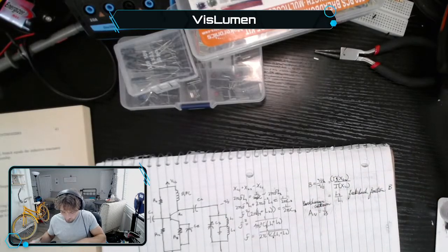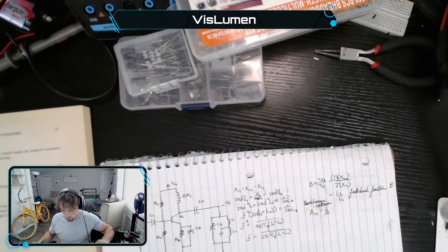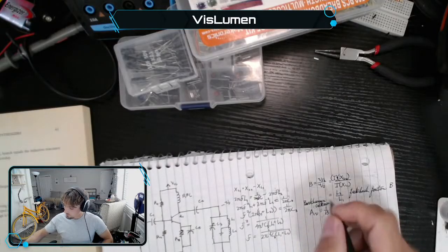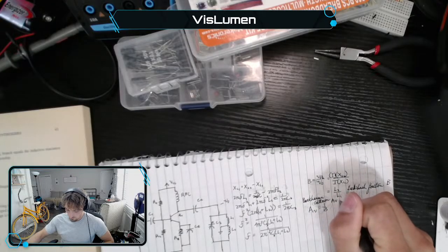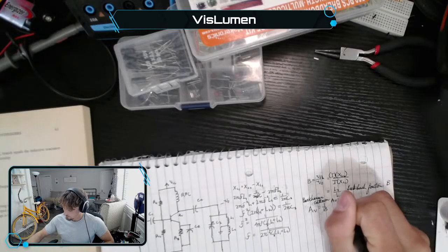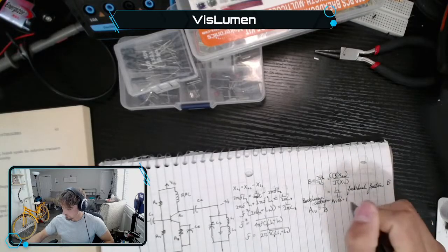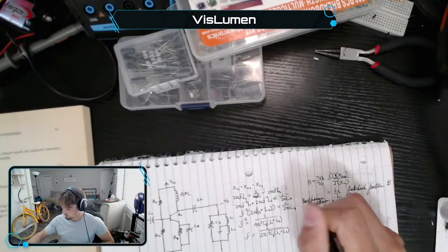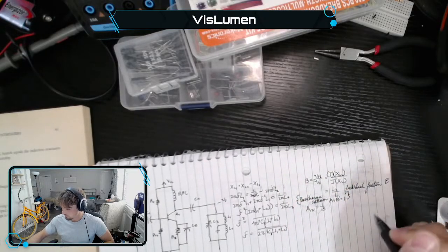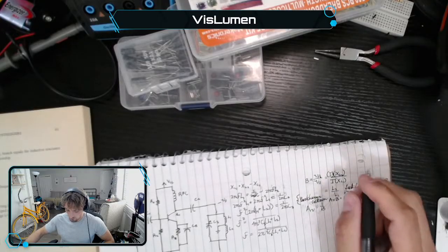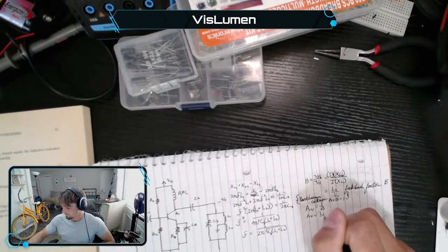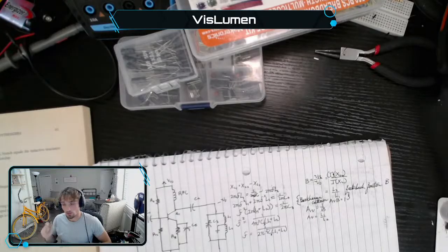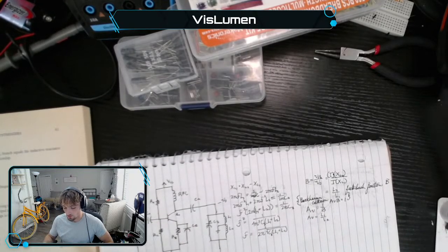Yes, okay. Did I spell that right? I did. Criterion for oscillation. Criterion, AVB product must equal 1. AV B equals 1. That's Barkhausen criterion. Yes. Okay. AV equals 1 over B. AV equals L1 over L2. Yes. Okay. Barkhausen criterion so that we can sustain oscillations.